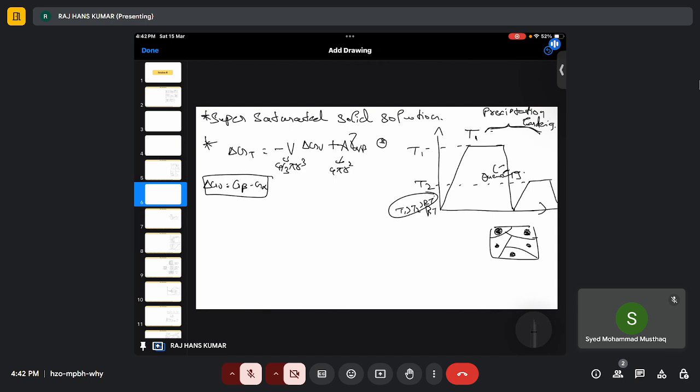Now again, this is for the case where there is no strain or there is perfect matching. We are talking about coherent precipitates, right? There is no mismatch. Now, if I try to find the critical radius, r equals r star will be equal to minus 2 gamma alpha beta upon delta GV. I have proved this many times in previous sessions, so I'm not going to prove it again here. I'm going to directly use that relation.